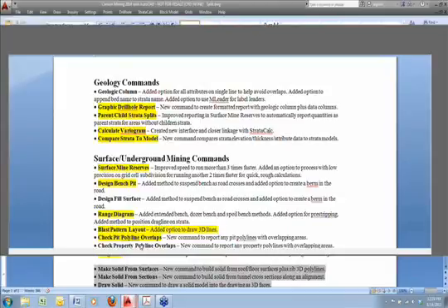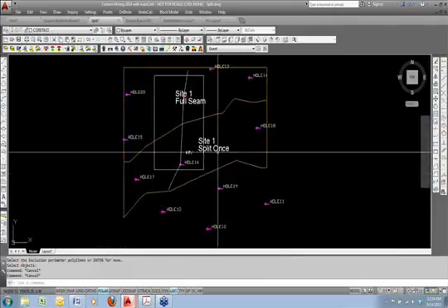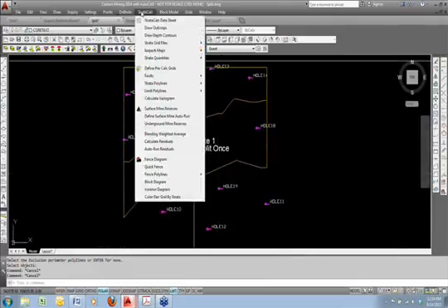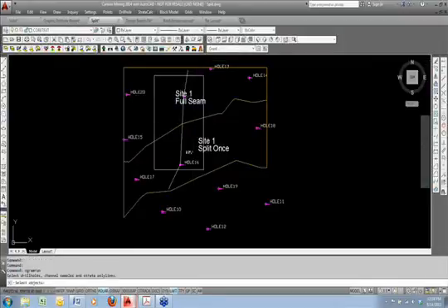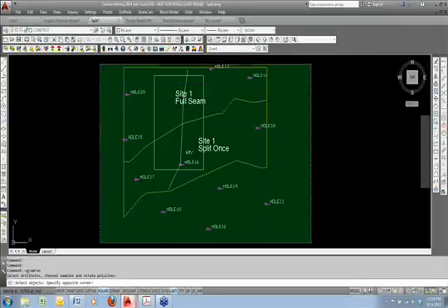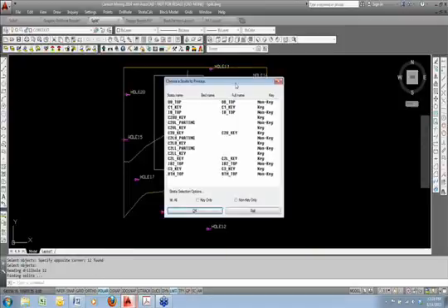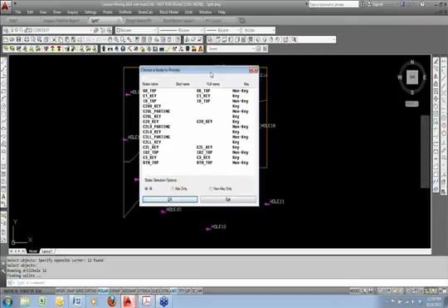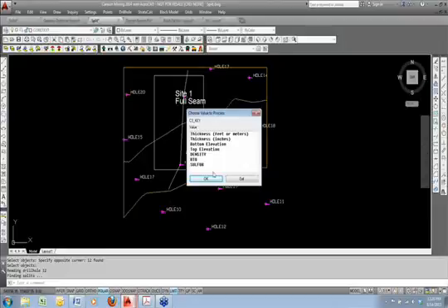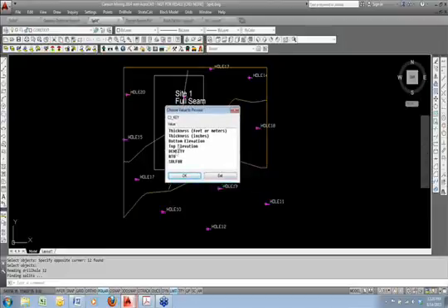We can do it in the same drawing. It just uses any drill hole configuration. It's found under Strata Calc, calculate variogram. So for those of you who are going to be doing kriging, the same command will apply to 2D and 3D kriging. Our 3D kriging would be used in the block model. The 2D kriging is used in the making of grids. So let's say we want to analyze the C3 seam here. I'll hit OK. Then you just choose a value to process.